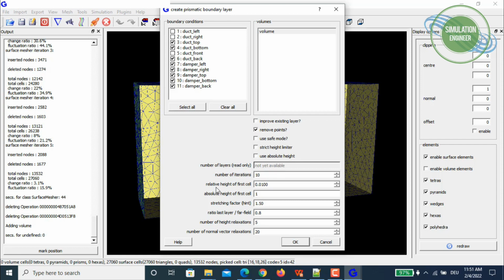If you are really looking to use low Reynolds number models and you want to get y plus of 1, and you want to resolve till the end of your viscous wall. But normally, even for different kinds of computations, with my experience, you get very decent y plus values if your settings are okay.